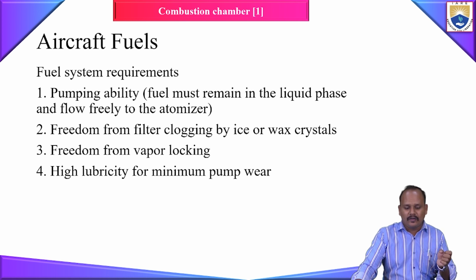and it should freely atomize. That is, it should flow freely through the fuel injector. The atomizer is nothing but your fuel injector. That is the pumping ability. And freedom from filter clogging by ice or wax crystals, which is because of the temperature change. So there should not be any clogging problem for your selected fuel.